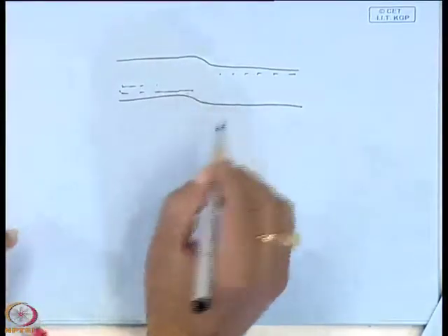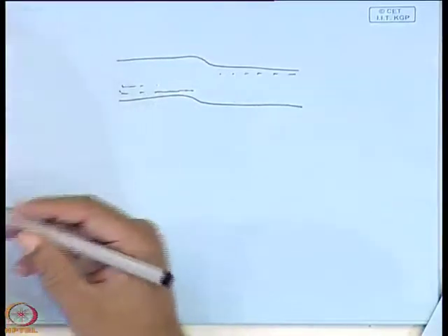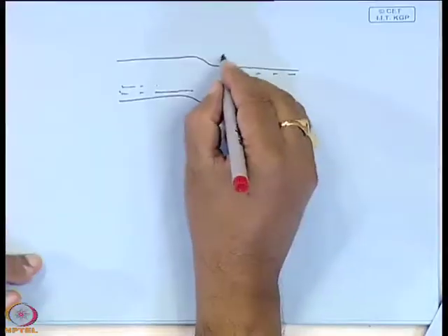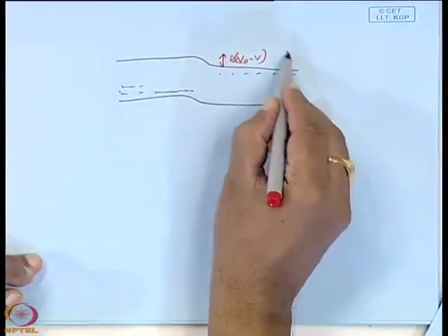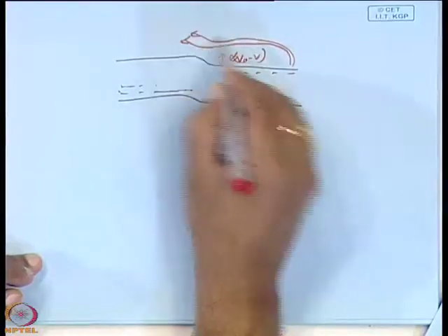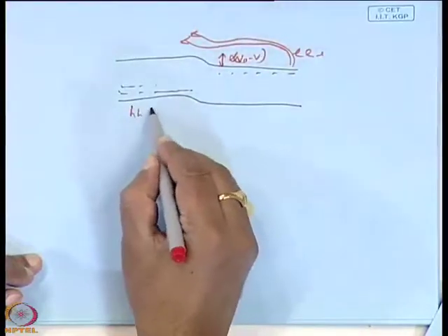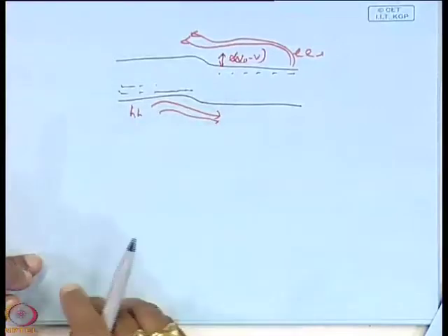Remember that now there will be no alignment of the Fermi level. Why? You have broken the equilibrium, because you have connected a voltage source. Only during equilibrium will there be alignment of the Fermi level. Okay. Now, this amount is E V0 minus V. So, diffusion of electrons will take place and holes will diffuse from this side to that side.